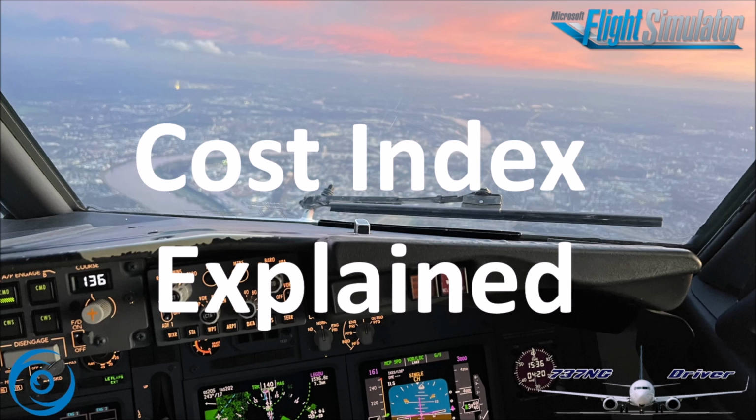Now if we had the very same flight with a cost index of 999, our optimum would be just flight level 268 with a maximum of also 268 and recommended of level 260. Now you may wonder, why is the optimum or maximum altitude actually lower than with a higher cost index? And that is rather simple, because the airplane may be thrust limited or it may be buffet limited at high altitudes. And in this particular case, our Boeing 757 would have to fly at a much lower altitude in order to be able to fly these airspeeds.